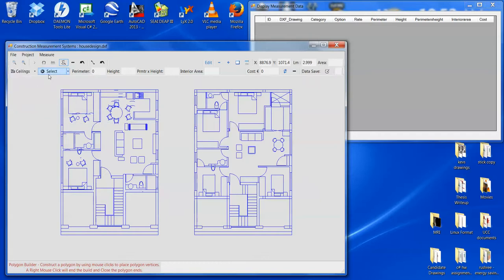We have ceiling options as well, 5 ceiling options. So screw fix standard plasterboard to existing ceiling joists. Screw fix 2 standard plasterboard to ceiling joists. Screw fix 1 foil back to ceiling joists. Suspended MF ceiling, screw fix to the underside of a concrete slab, which would be in modern concrete slab houses. And suspended MF ceiling fixed to underside of concrete slab with acoustic insulation, 150mm. So there are options. We keep going here.